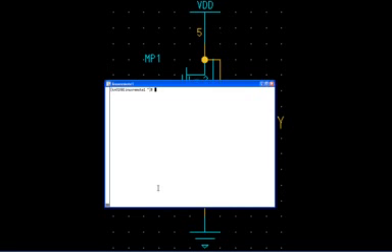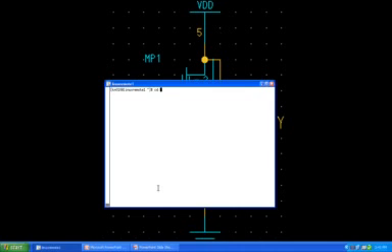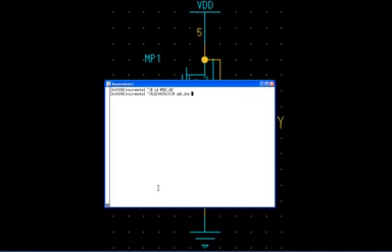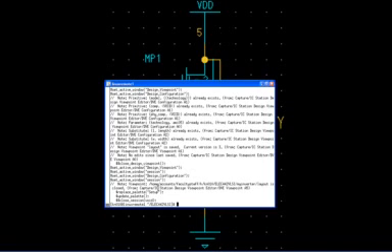In order to create the layout, the first thing we need to do is create the design viewpoint. For that, first let's go into our Mentor Graphics working directory. Type in cd $mgc_working directory. This will take me to my ELEC 442 VLSI folder. Now type in adk_dve. The name of my design is called my inverter. The technology I'm going to use is AMI05. So I type in adk_dve space my inverter space -t space AMI05. Enter. So this is going to create a design viewpoint for me so that I can do the layout based on the schematic.